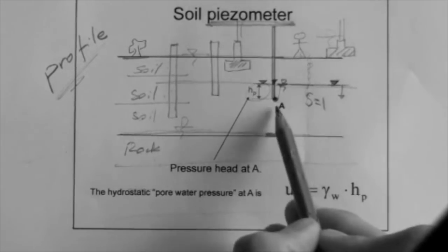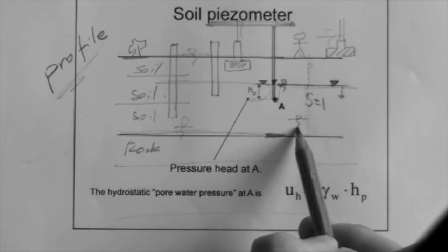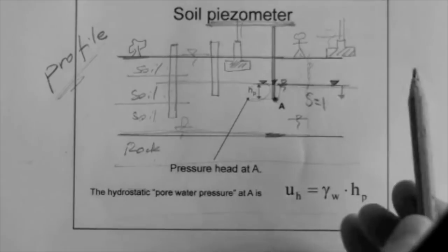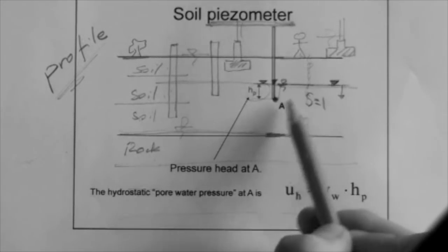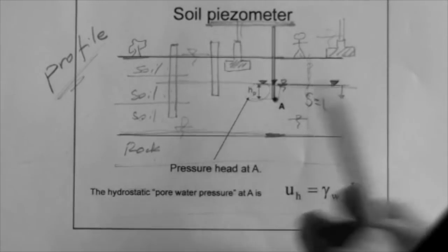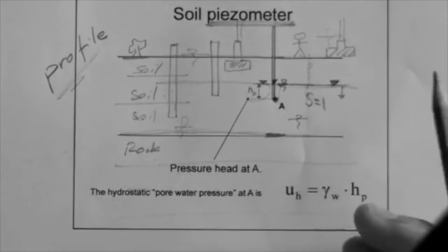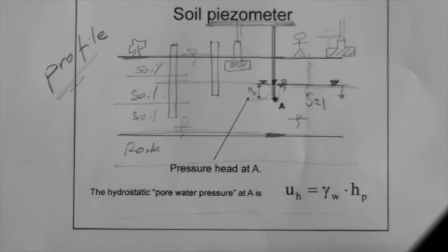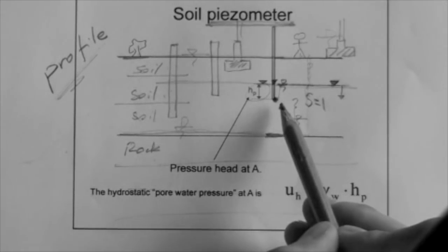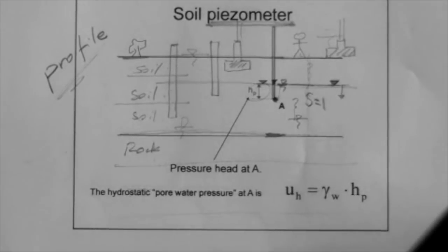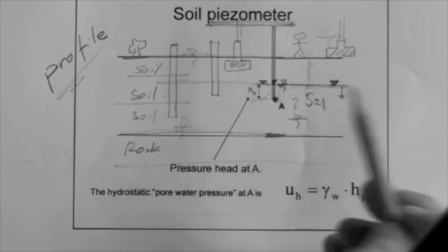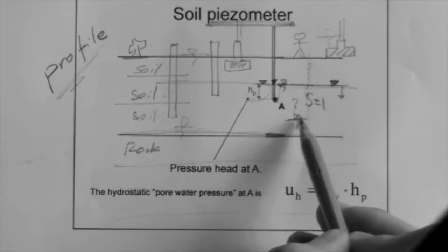Now, what happens if the water table is down here? Well, the point is above the water table. So we assume that this point is in a location of dry soil. There's no water, so the pressure head is zero. We cannot even calculate the pressure head. You could say, well, hold on one second, the pressure head is negative. No, the pressure head is not negative. The pressure head is nothing. We don't even think about it, because the point is in soil that is dry. That is in the case where the water table is here.